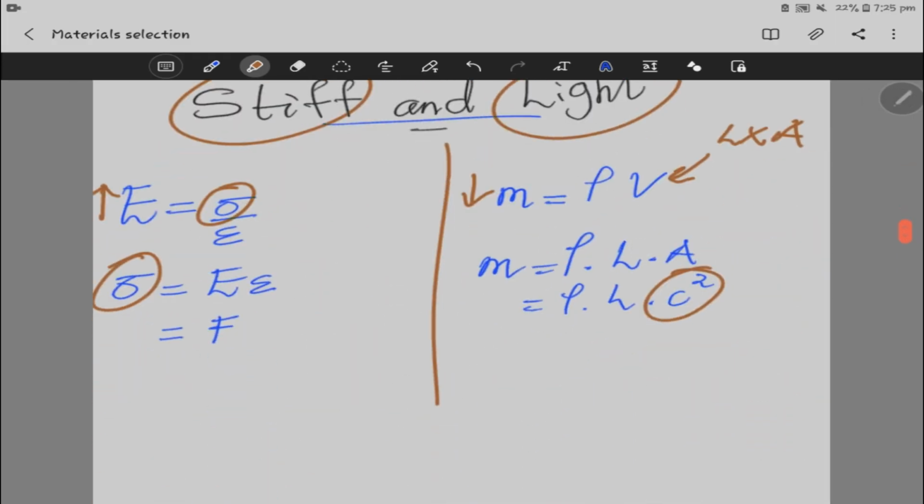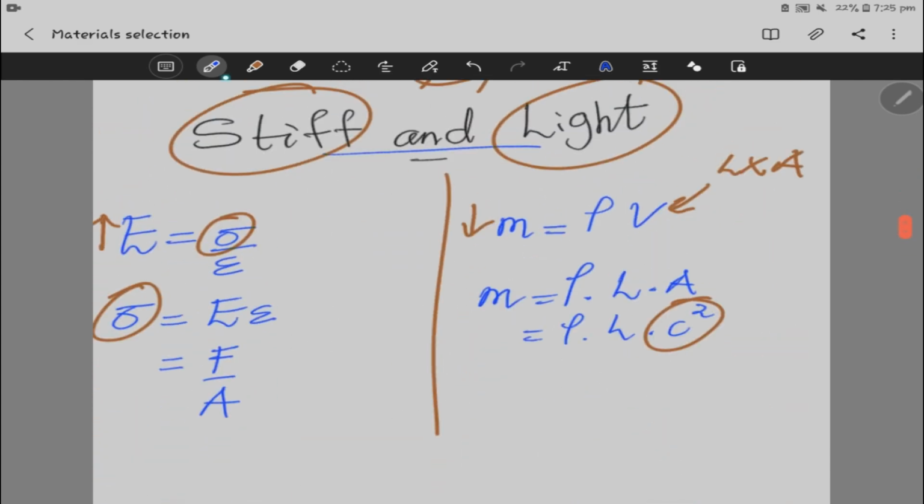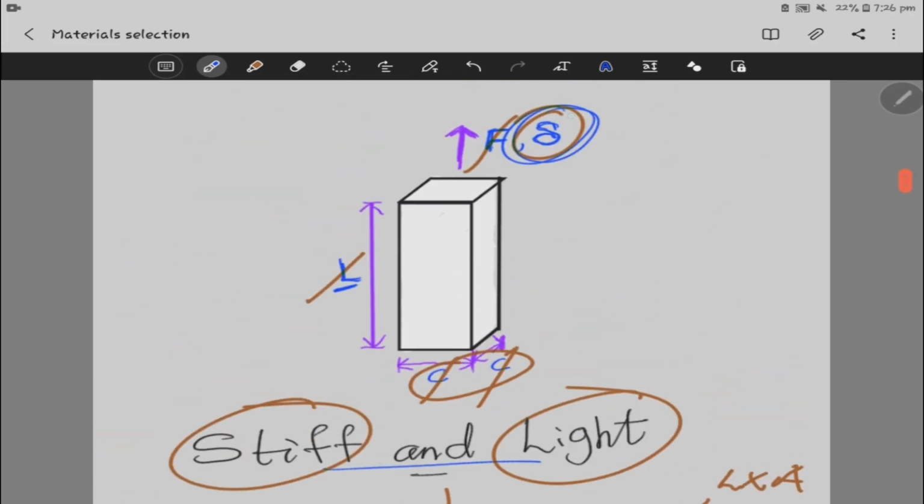So we know this stress is the same as force per unit area. The next thing is to eliminate this one here, and we know that's extension. This one is E, and the strain is the change in length over initial length. Multiplying all this, it ends up being E times the extension that was given.